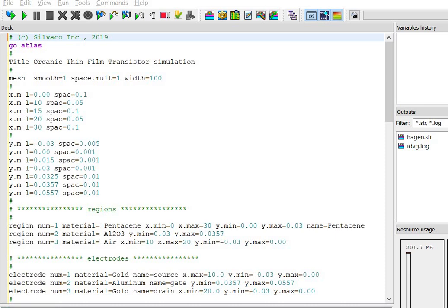This section defined the dimensions of the individual layer along with the position of the electrodes. The layer of the insulator and active organic materials are defined. The source drain contact in top contact structures are positioned at the top of the organic semiconducting layer, whereas in the bottom contact structure, the contacts are placed below the organic semiconductor layer.